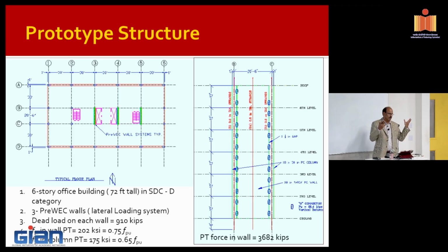So each structure has inherent damping. Some are at the molecular level, some are opening of cracks and closing, some have bolted connection, the friction induced, the thermal energy dissipation take place. A lot of things happen. We typically assume that number to be in the 3 to 5%, right? So the damping is an important piece. Make sure you understand that any structure will have 3 to 5% damping, right?